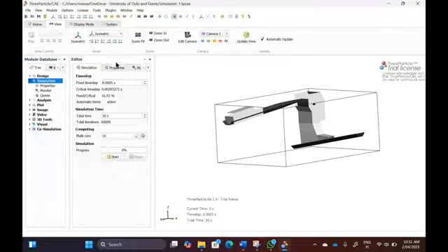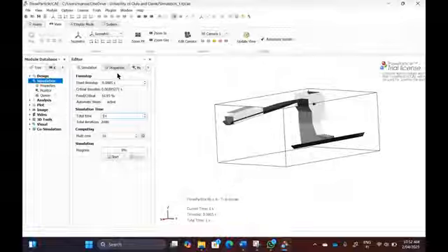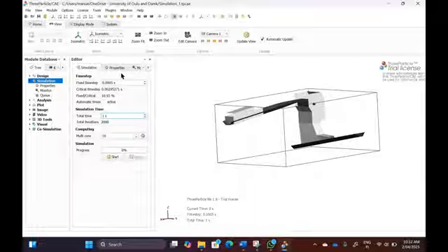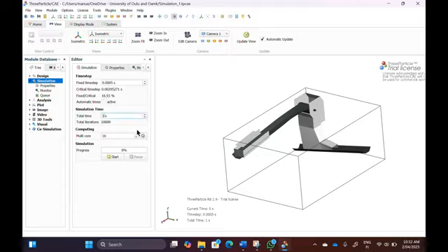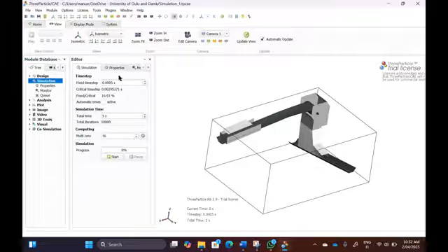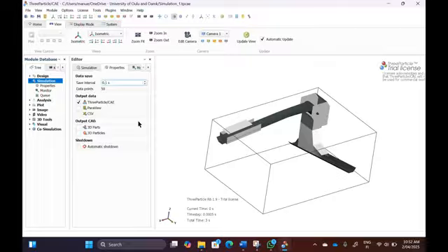Rename that. That's the tube. Okay, I have the simulation and I say file import, and now I import another thing, and the segment is in there as well. So I can import and import and import, and it doesn't replace my initial one. If you want to have only the segment, you need to set a blank simulation first. If you want to change to the segment, just select new, and then import the segment.